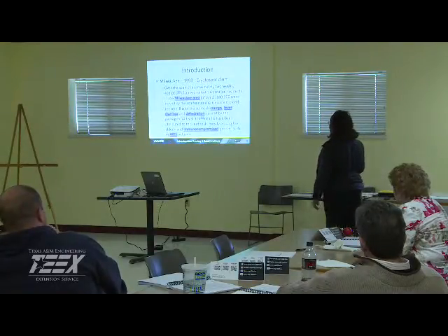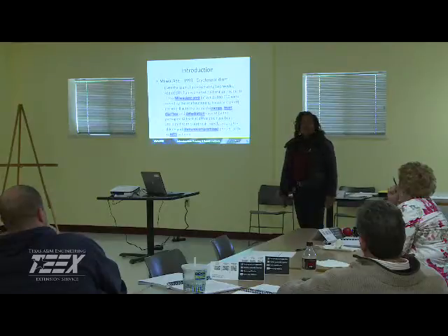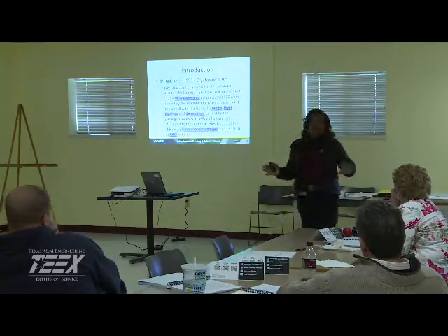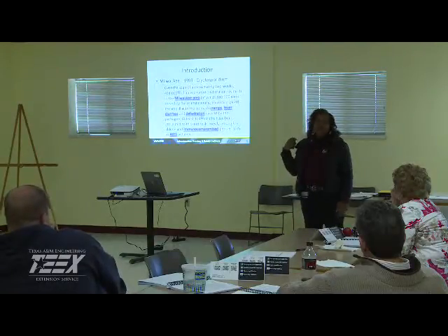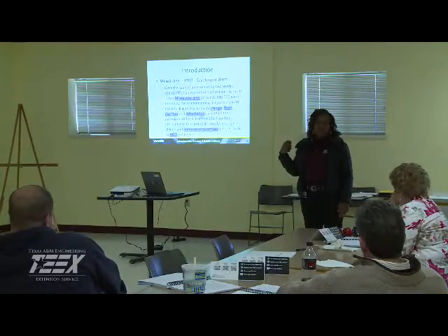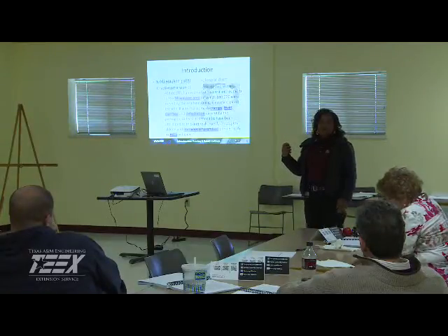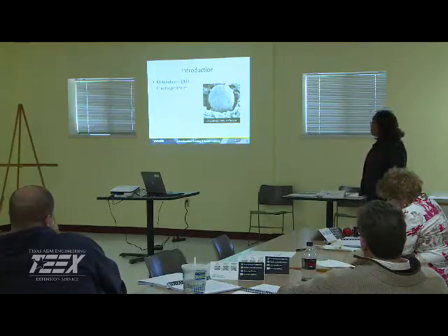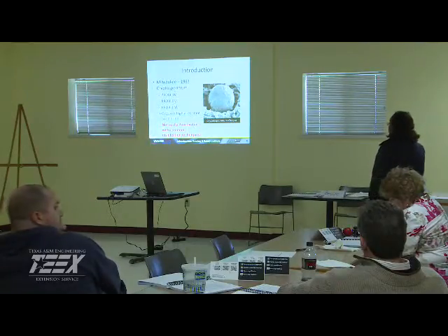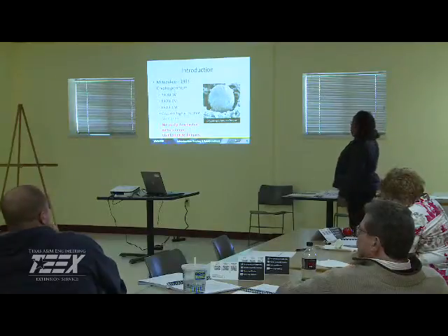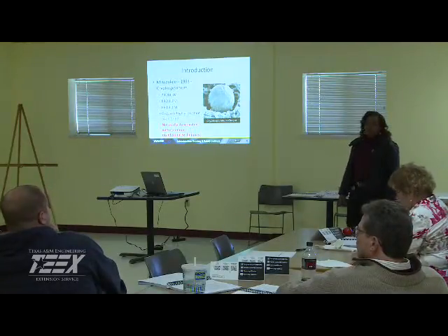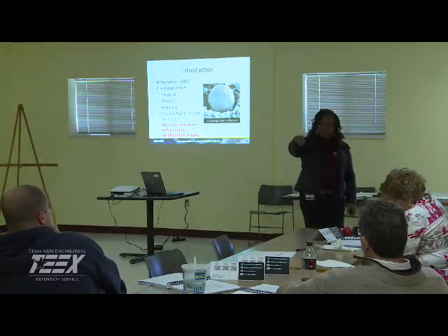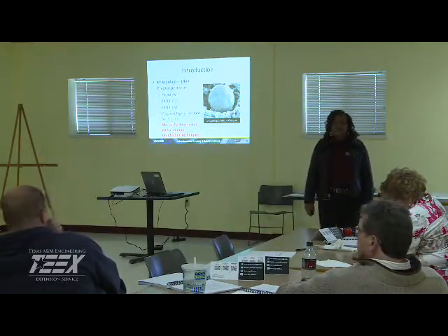What's unique about cryptosporidium is that we disinfect the water, and usually with disinfection we think that takes care of all organic material. Chlorine does nothing to cryptosporidium. It forms an oocyst which protects it from chlorine, so it is highly resistant to chlorine. That's the reason there is a problem. They have to be filtered out.